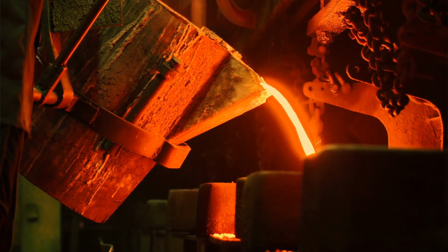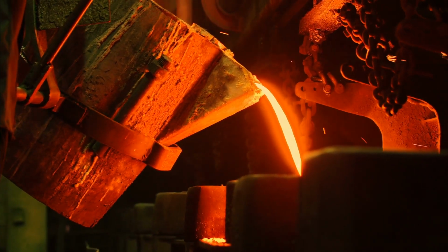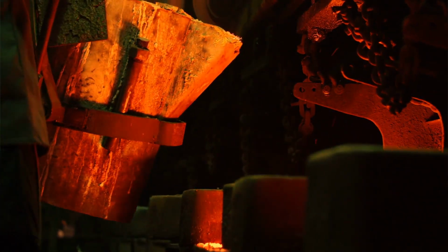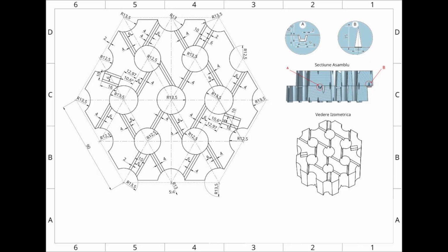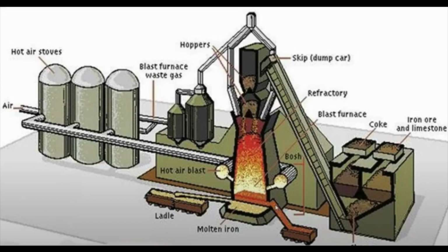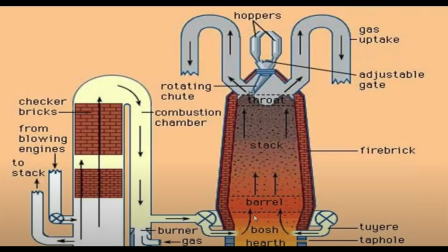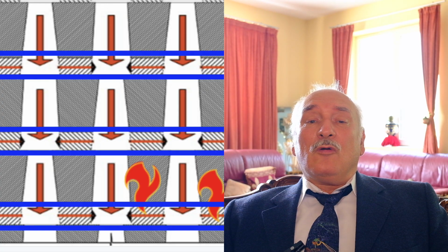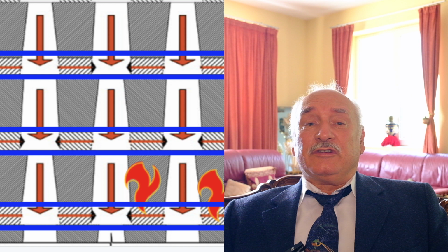It is the volume of the voids that determines the heat transfer surface through which the heat enters the brick from the burner gases, and the heat leaving the brick, which is taken up by the hot air that feeds the kiln. In the regenerator, the technological efficiency is directly proportional to the number and size of voids in the brick, to make the temperature of the air blown into the kiln more efficient.